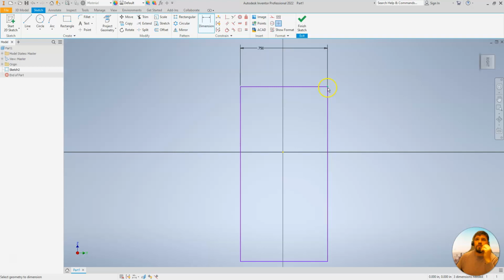Now remember this, do not click the dots, because even though it's doing the same thing for you currently, when we get into more complex modeling, it really screws things up. Because complex modeling has various shapes and surfaces, and when you don't dimension them correctly, which remember, dimensions are constraints, whether linear or aligned, it will jack up your model when you're trying to change one dimension. So I'm going to delete that, and I'm going to make it again by just touching the line. And I know that needs to be 1.5 inches or 1.75 inches.